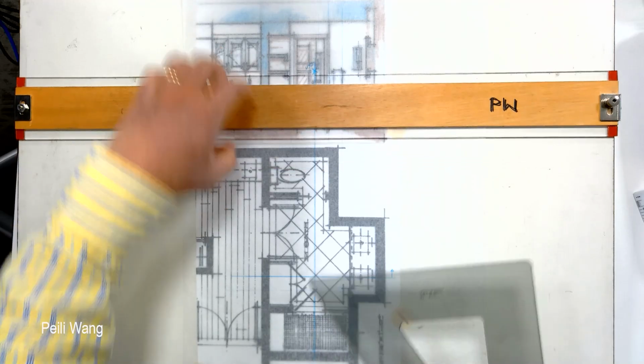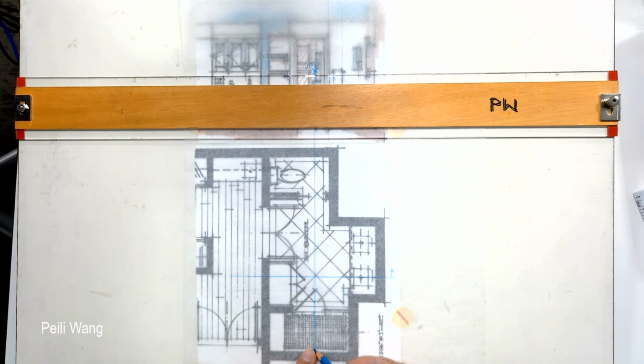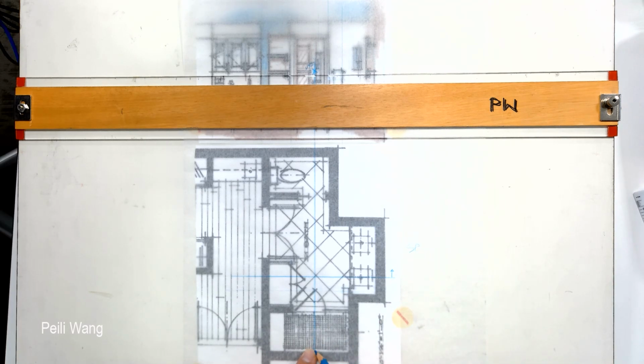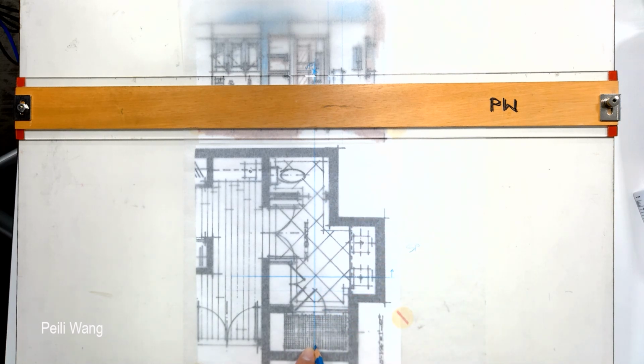So now we go back to the floor plan where your station point, SP, you can pick any point along this line. I can stand in here. If I give you a camera, you take a picture. You can stand here. Where do you want to show? I want to see this side. Take a picture. I can stand here. Where do you want to stand? You decide. So this time I decide I stand on the corner.